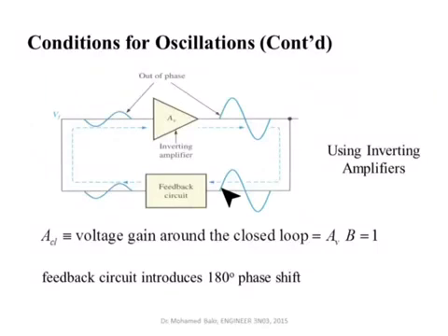In other words, if this signal has an amplitude of 1, the output signal will have an amplitude of 0.1, but with a phase inversion. So here the gain AV is -10, and here I can simply call this a gain or attenuation. The attenuation is -0.1. You reduce the amplitude to 1/10, but you also add phase shift.